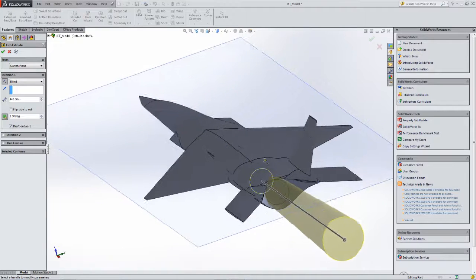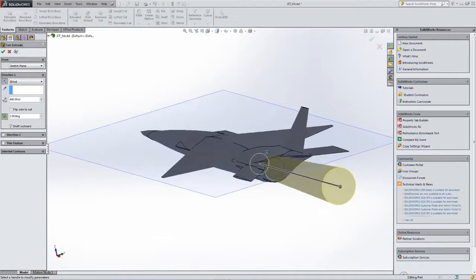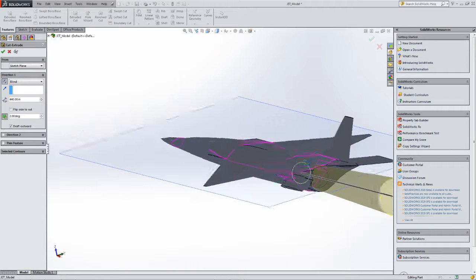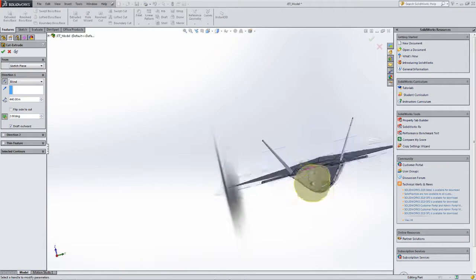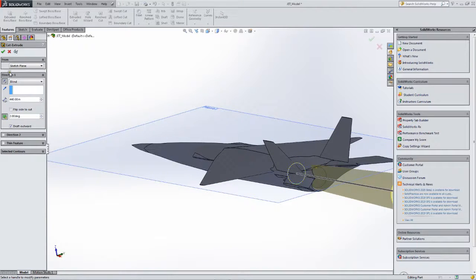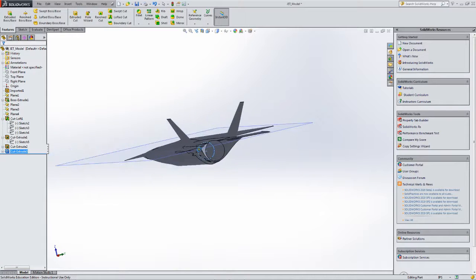This is not for drawing the airplane model, because probably the rear of the engine would be here in the real airplane. And so this hole up in here would all be pretty much constant diameter. But this extruded cut is to make sure we have clearance on the sting. So we do that, cut away just a little bit more of the model, and now we've got a nice place to put the sting mount.